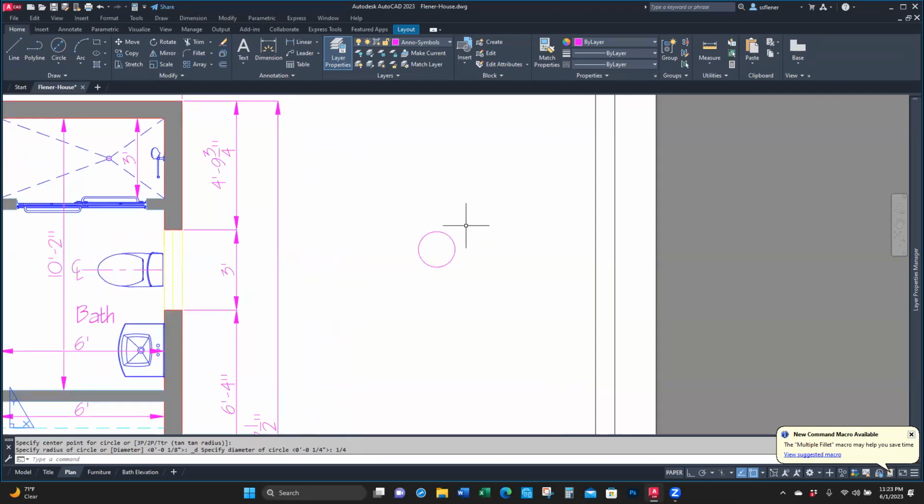And we are going to do a triangle. So we're going to switch the rectangle to a polygon. We're going to put in 3, enter. And we're going to specify the center of the circle. And it's going to say inscribe in circle. Okay.